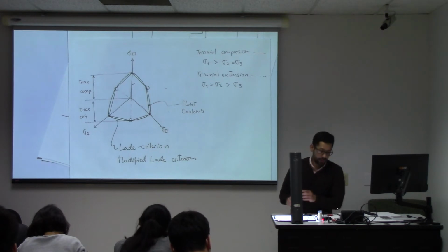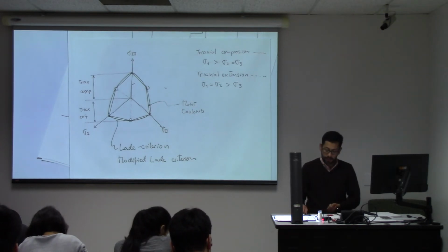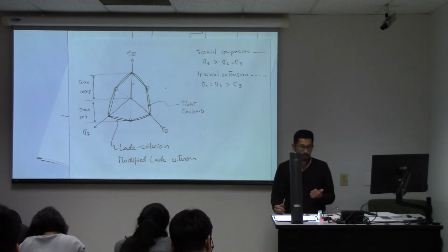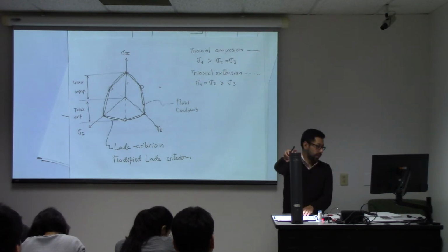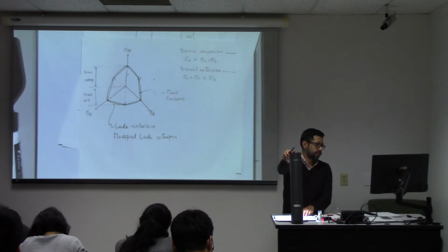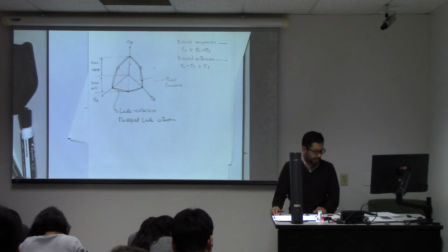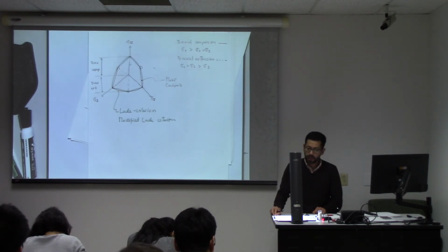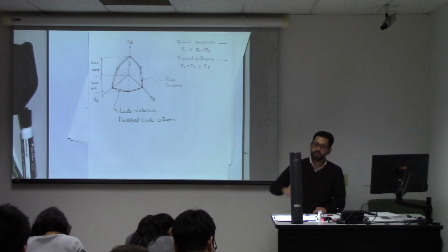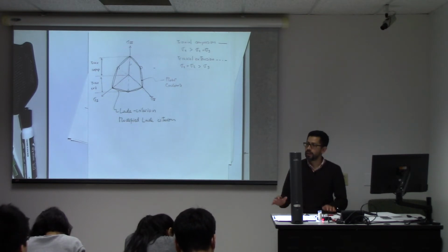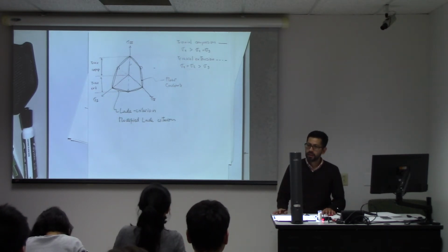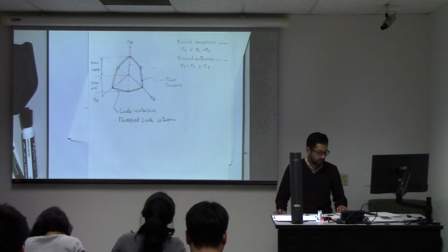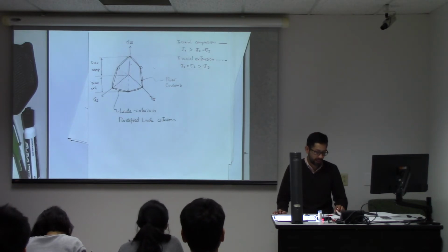And in that criterion, you have stress sensitivity. You can acknowledge the difference between triaxial compression and triaxial extension, and it's also smooth. So it's kind of the whole deal. It has everything you can ask for in the modified Lade criterion.